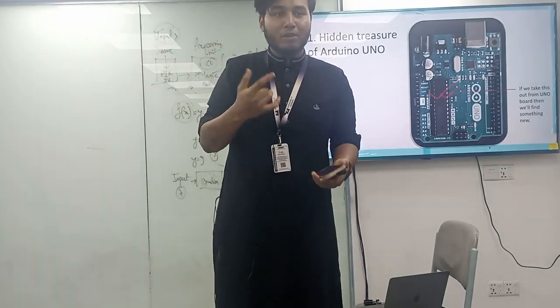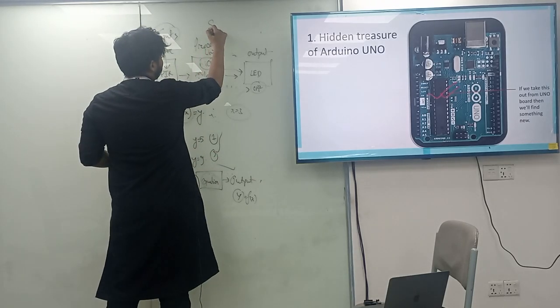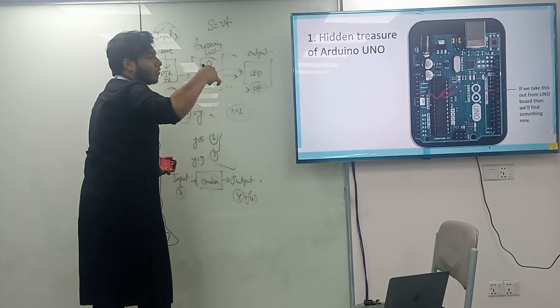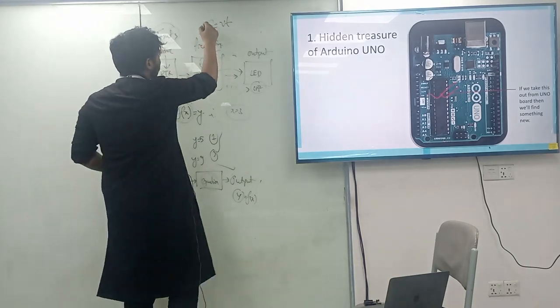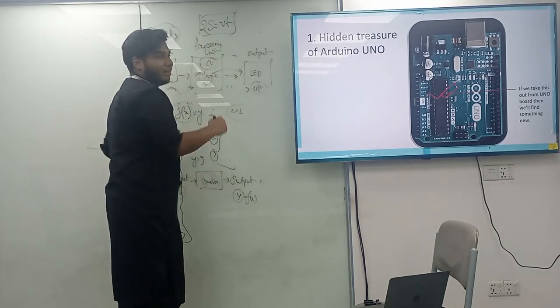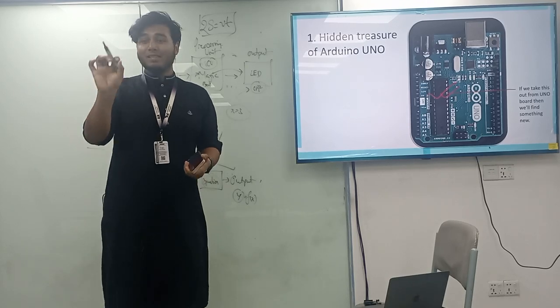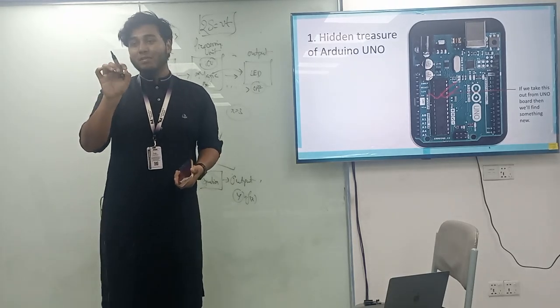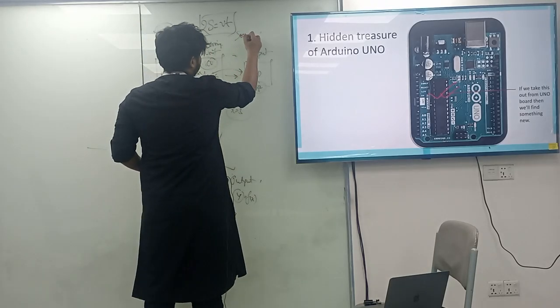So how is it possible? It means you have come to know that S is equal to Vt. Whenever you are hearing your own voice as an echo, it means 2S is equal to Vt. Isn't it? Yes, sir. Okay, so that's the simplest physics equation which has been implemented in the sonar sensor.